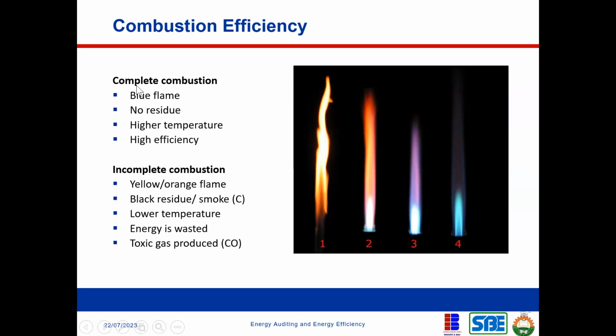Now combustion can be complete and it can be incomplete. The whole idea for us as energy auditors is to make sure that a combustion process is complete. Because if the combustion process is not complete, it means that you have unburnt fuel. There is fuel that should have opened up and released its energy that is not combusted, so it leaves as waste. So we need to make sure that the combustion is complete. How do we make sure that the combustion process is complete? We need to introduce excess oxygen. If there's no right amount of oxygen in that combustion process, it will not be complete.